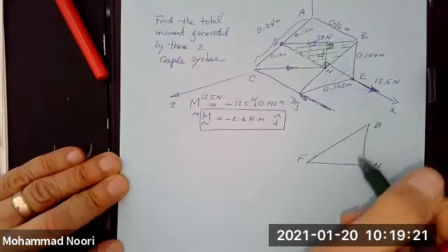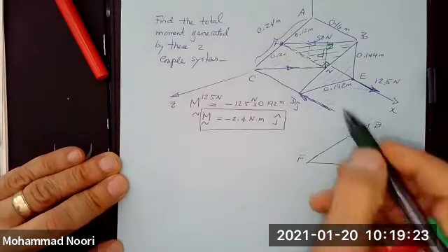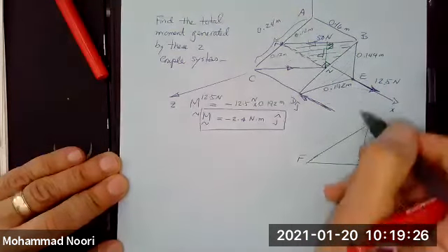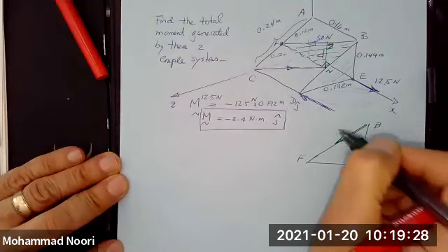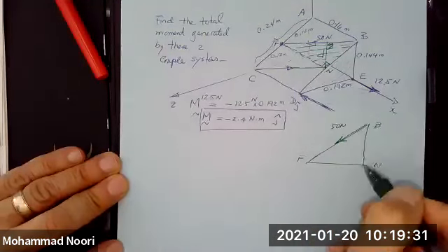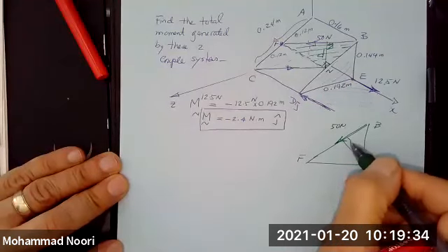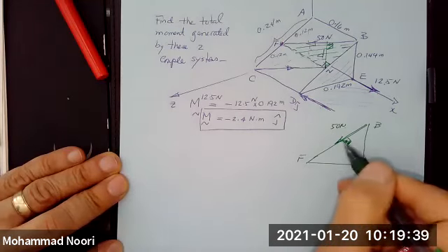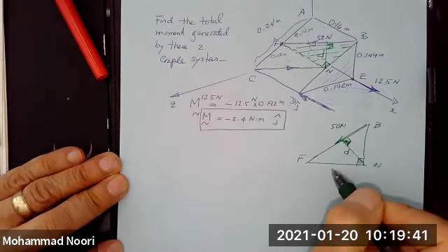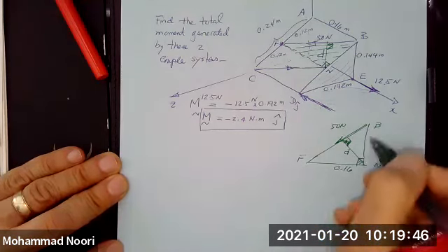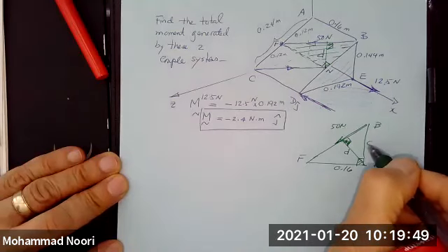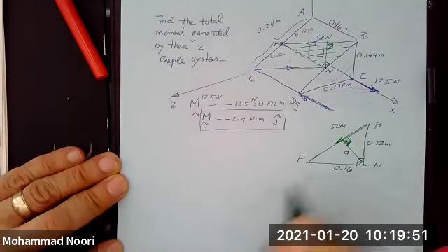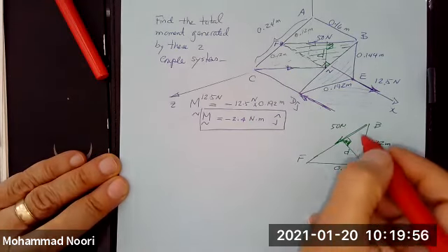So if that's N, this is that triangle, that D would be, in other words, this force is that 50 Newton, and this is the distance, which is the height in this right angle triangle, okay? So this is D. And these sides are given. This is 0.16, this is 0.12 meter. Any problem with the geometry here? You can visualize that, right? So what is D?